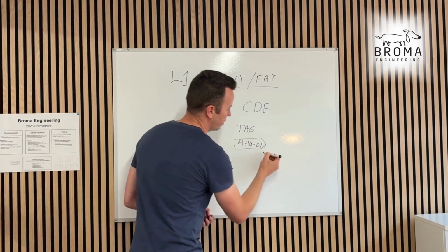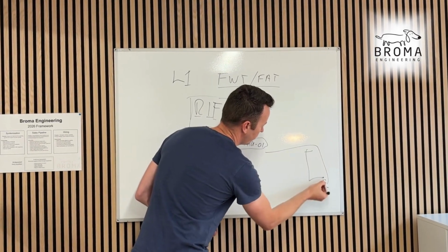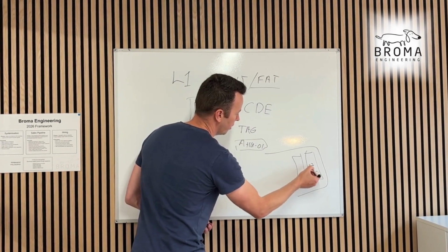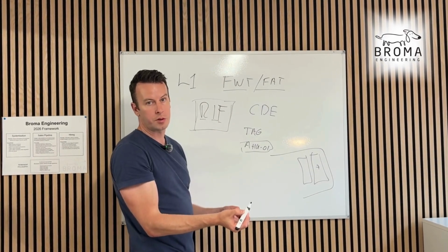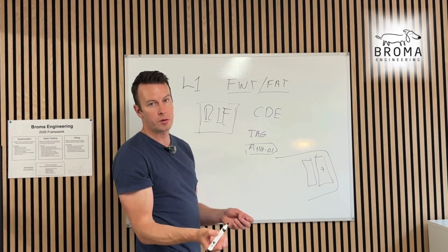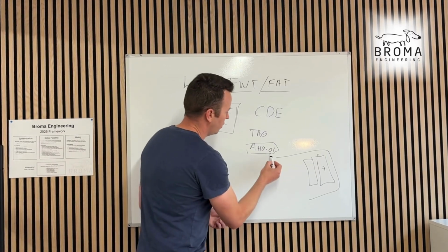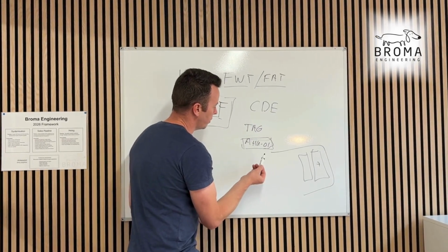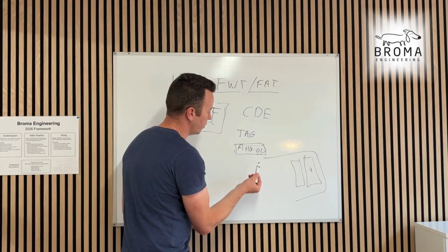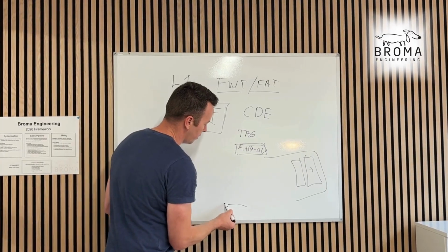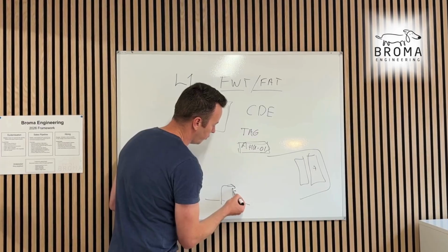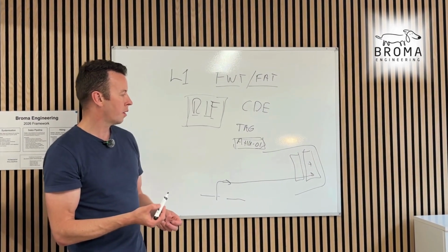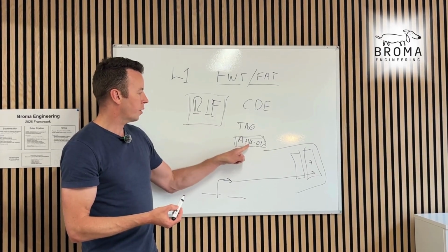This is the one that goes into the back of a room in here. I suppose we have a row of them. We don't want to bring in AHU number 2 first and put it here. Then we're going to have to change the nameplates and serial, you know, it's going to be a mess making new nameplates. So be careful if you need to sequence them. Sometimes you won't. You'll be dropping them onto a place where you can move them around. But if you're rolling them in through a door, we'll say over here, you have to roll them sideways all the way down to the bottom of a cul-de-sac. Make sure your sequence is right.